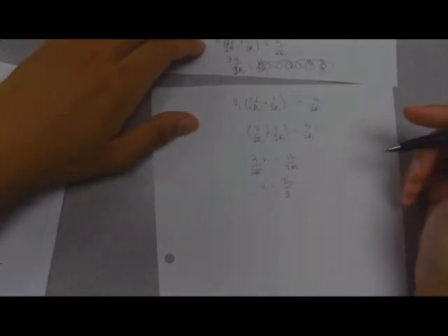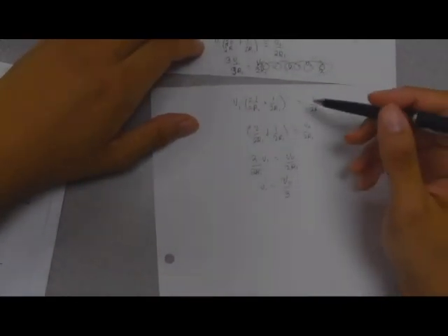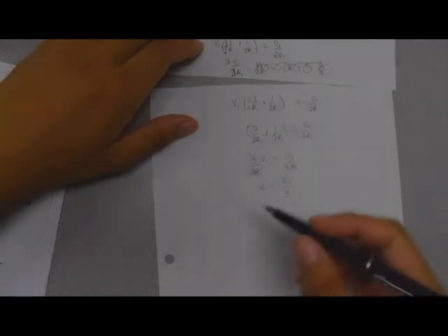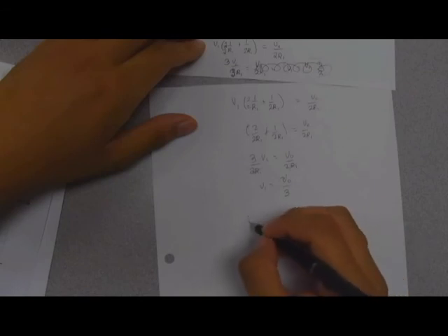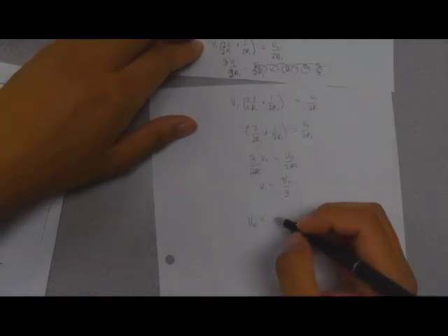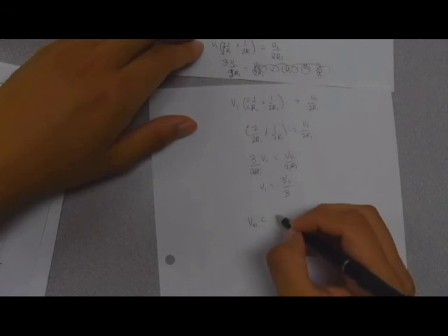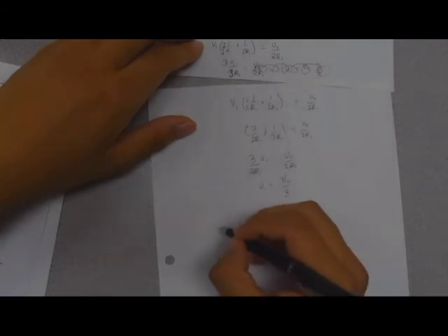Now to draw this, we have to find out where the op-amp is going to saturate. We have to look at where V out can go. V out is going to be between these two values: less than 9 volts, but greater than negative 12 volts.